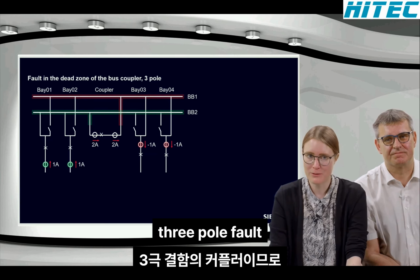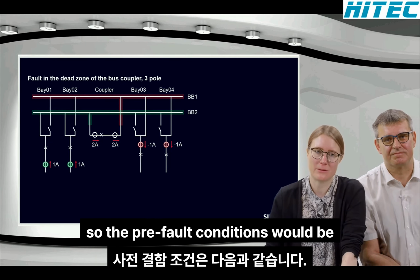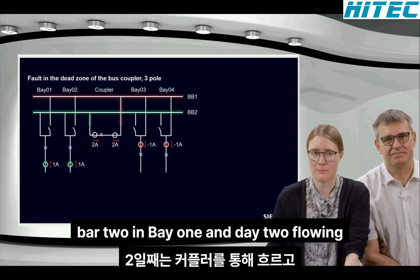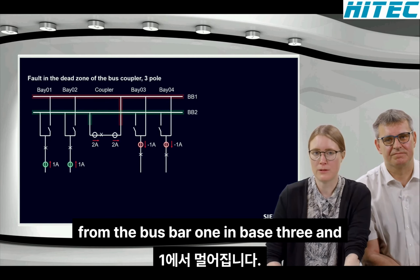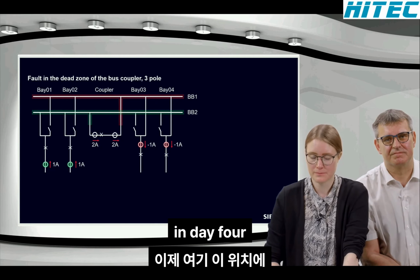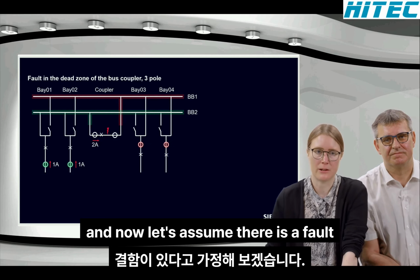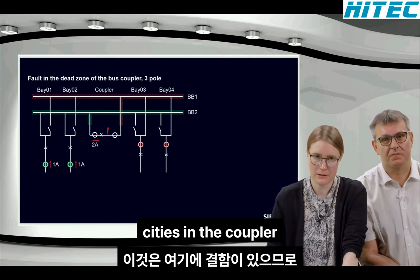in a 3-pole fault. So the pre-fault conditions would be that current is flowing towards busbar 2 in bay 1 and bay 2, flowing through the coupler and flowing away from busbar 1 in bay 3 and bay 4. And now let's assume there is a fault at this position, between the 2 CTs in the coupler.